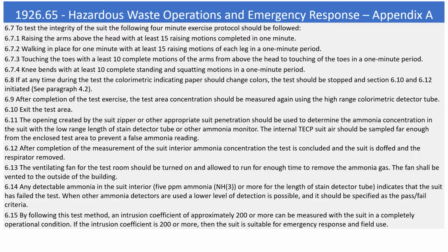6.12. After completion of the measurement of the suit interior ammonia concentration, the test is concluded and the suit is doffed and the respirator removed. 6.13. The ventilating fan for the test room should be turned on and allowed to run for enough time to remove the ammonia gas. The fan shall be vented to the outside of the building.